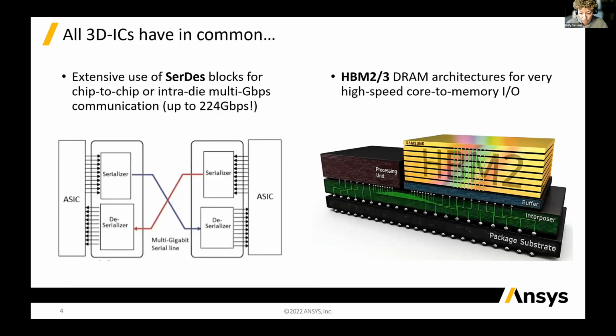Two important aspects of heterogeneous integration are the substrate technologies and the chiplet-to-chiplet communication interfaces. Substrate technologies mainly fall into two categories: silicon interposers like CoWoS and organic interposers like InFO. Physical communication interfaces can be serial, where SerDes blocks take care of the conversion of parallel data input to serial data output, and vice versa.